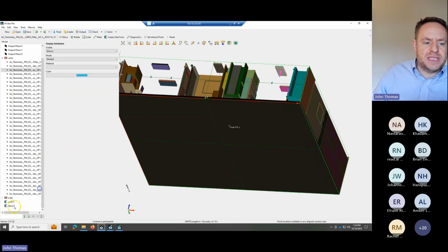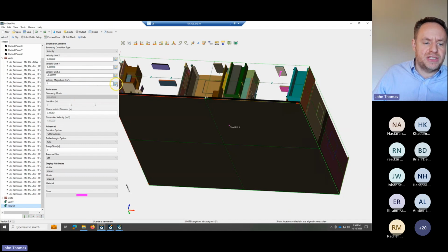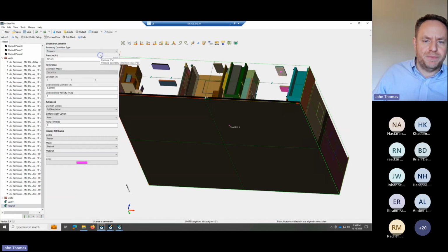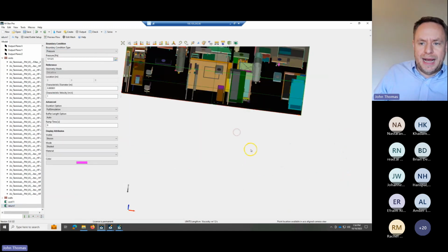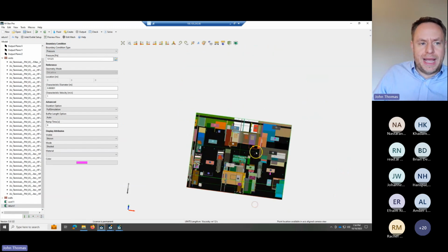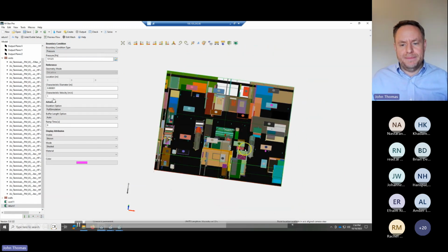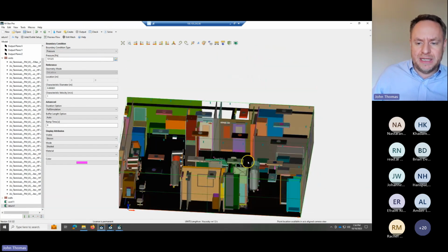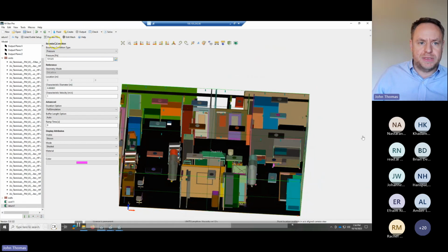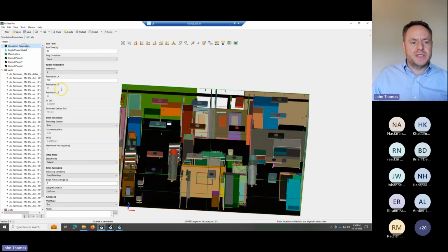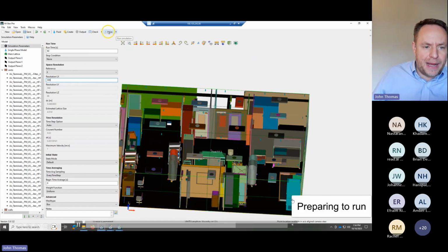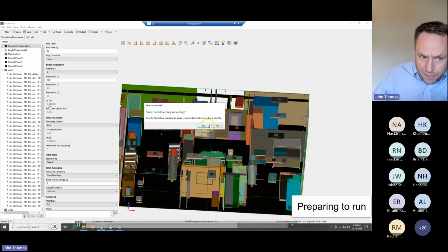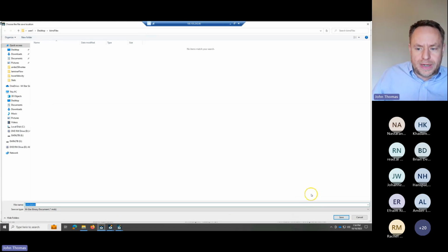Let me go ahead and set this resolution to be something more appropriate. I'll set the return to just be a pressure boundary condition because that's where fluid's coming out. Let me go ahead and push this around, and I'll change my resolution here. But again, just my one inlet, that's all I need. But I could go through and snap these guys routinely. I'll go up here and choose the resolution. Again, I'll be modest since I'm running on my laptop. It's this example on my laptop, but it's got a 4 centimeter grid spacing, which is fine. I'll go ahead and kick this guy off.